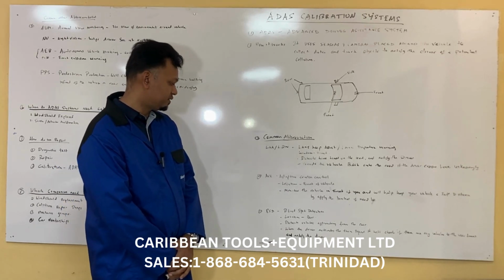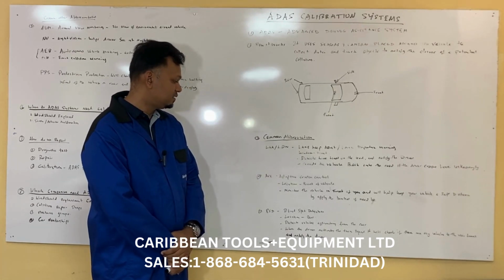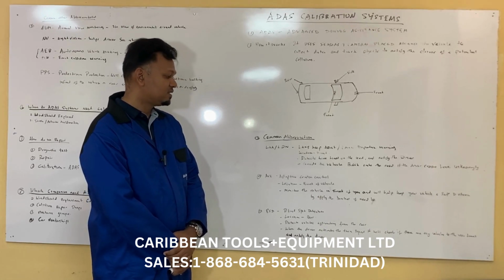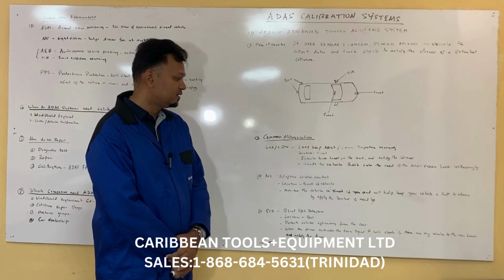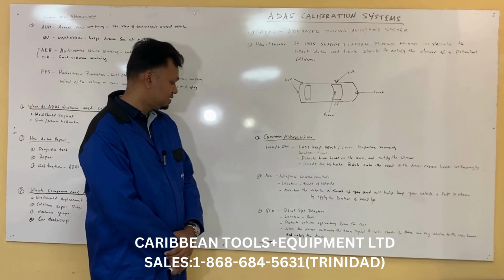BSD, blind spot monitoring. The location is to the rear. It detects the vehicle approaching from the rear. When the driver activates the turn signal, it will check to see if there are any vehicles in the rear lanes, and it will notify the driver.